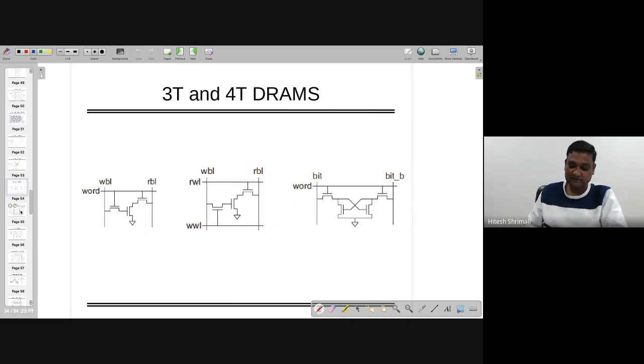The third technique is similar to what we have seen in the case of SRAM, but it does not have PMOS because PMOS is not required. It's a redundant thing. But if you want to use it, you can use it. There is no problem, right? That is also one of the advantages. But when you are using it, it's increasing not only two transistors in a cell, but as many cells as you have, it will be multiplied by 2, right?